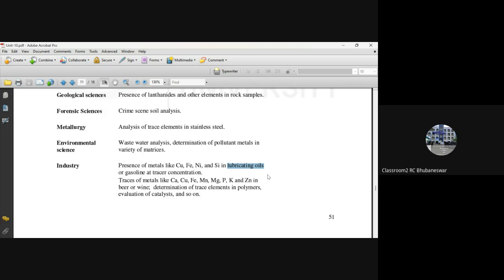But the thing is, as I was telling you, you need to note down the detection limit. Okay, by fluorescence spectroscopy, it is sensing 1% contamination of kerosene in diesel or petrol. If it is sensing that, it's good. If some other method is sensing only 2%, then we may not use that method.